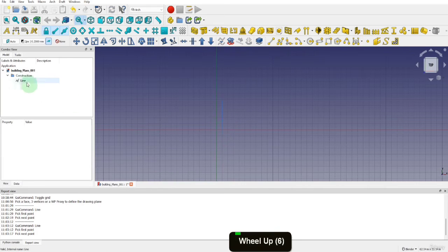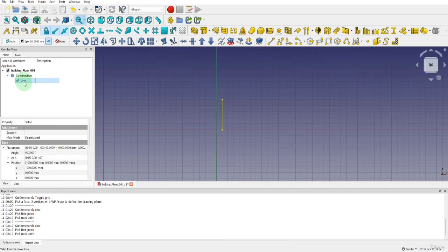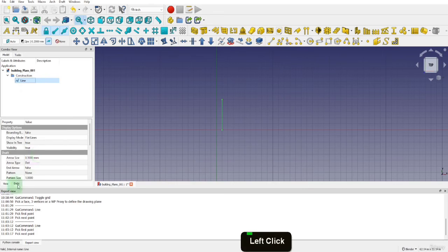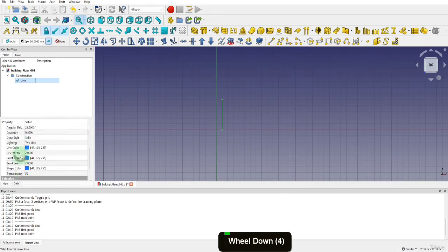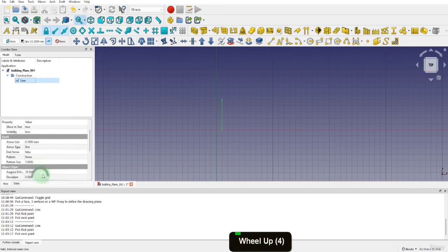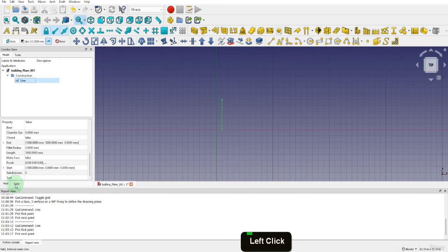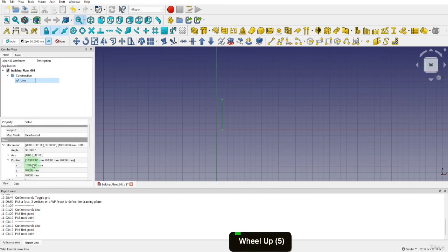As we are seeing, you can use the object's data to modify an object's property after creation. In the View tab, there are properties associated with an object's visibility, color, width, or whether it's selectable or not. Let's use this line to get the second point of a rectangle. So open back up the Data Properties tab. Come back to the Placement tab and we can input 16,000 mm into the X location.